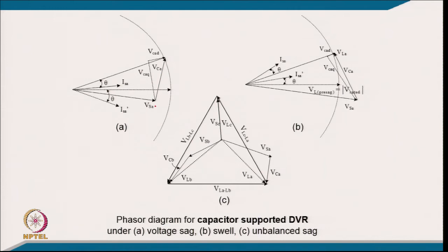So, what you have to do now is inject the voltage, and typically this is the original load current, with the voltage, and now the current will go this way. So, you have to inject the capacitive current, and this is the quadrature axis, this is the direct axis, and you have to maintain this voltage, which is the rated.